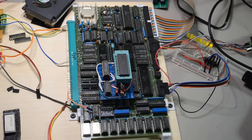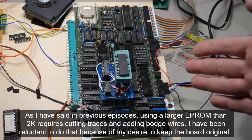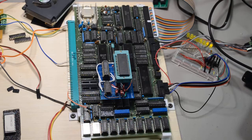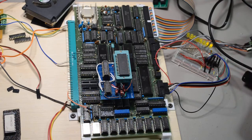Even if I get out the soldering iron and the bodge wire and make the changes I've lamented having to do in the last couple of episodes, because they didn't include real jumpers on the darn thing, I actually have to cut wire traces and add bodge wires in order to use an EEPROM bigger than 2K on this. And I wanted 16K. And the biggest this can handle is 8K. So I came up with the daughter board idea.